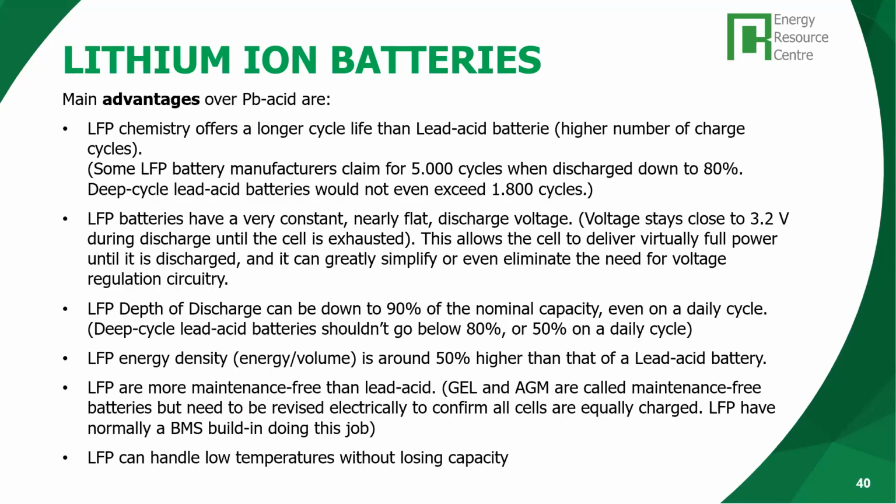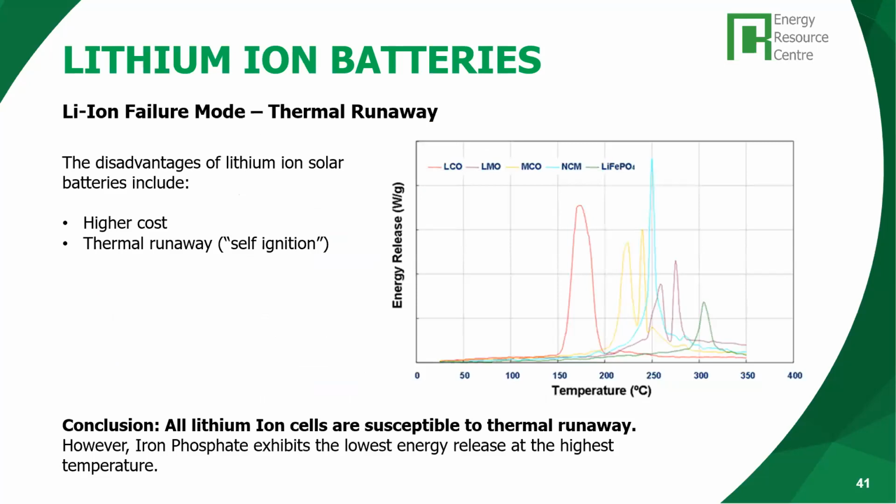Okay, for the advantages, I think we can skip this because we have already talked about that: depth of discharge, energy density. One aspect that was a little bit controversial about lithium-ion batteries is the self-ignition, which in the industry is more described as thermal runaway. Well, this could be the main disadvantage of lithium-ion batteries, together with the higher cost. But the higher cost, in a way, is compensated by the longer operational lifetime, okay?